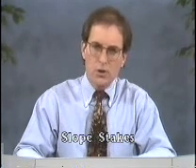When the design is complete, the construction phase of the project begins. Construction slope stakes are set at catch points at the intersection of the design section side slopes and the ground section. Position of the slope stakes can be approximated graphically from the sections or computed by solving an intersecting line problem. Because ground lines are usually measured to the nearest few tenths of a foot, normally adjustments to the calculated positions must be made in the field when the stakes are set.